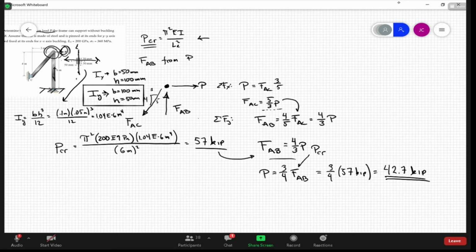You're going to design it for that combined loading like we did in chapter 8, I believe. Well, whatever it is, the combined loading chapter. Now you've got a design, okay? Then if you have elements that are in compression, you really need to go back afterwards and check: do they buckle? That's typically the workflow for designing these types of things. You usually don't design to buckle, all right?